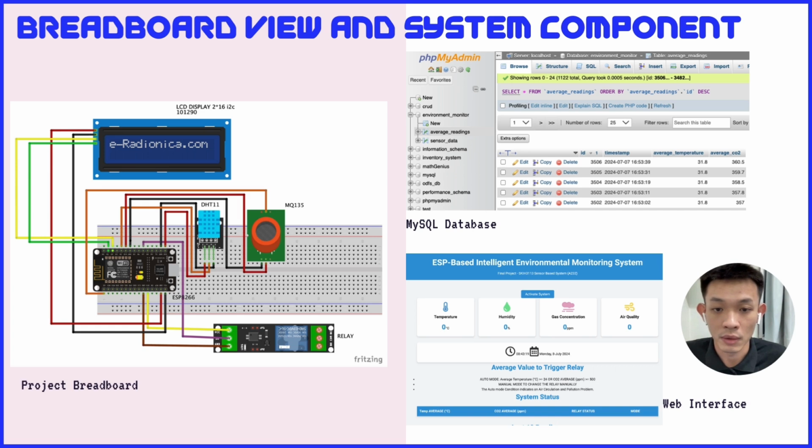Let's go to component 3, the MQ135 sensor. This MQ135 gas sensor is used to monitor the gas concentration, specifically the CO2 level, to assess the indoor air quality. It sends the air quality data to the ESP, which is then used to decide when to activate the ventilation system.